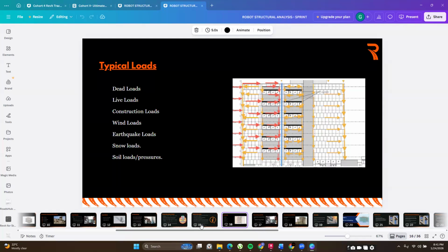If you are doing a structure, at least from where we are in Kenya, say that is above 5 stories or 4 stories, you have to do your wind simulation and have those results catered for in the design. So for today's class, to keep it simple, we are going to majorly deal with the gravity loads, and those are the dead loads and the live loads.